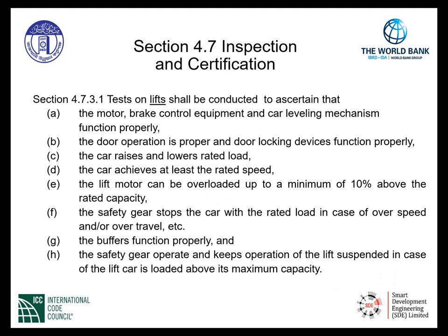Section 4.7.3.1: Tests on lifts shall be conducted to ascertain that A, the motor, brake control equipment, and car leveling mechanism function properly. B, the door operation is proper and door locking devices function properly. C, the car raises and lowers at the rated load. D, the car achieves at least the rated speed. E, the lift motor can be overloaded up to a minimum of 10% above the rated capacity.